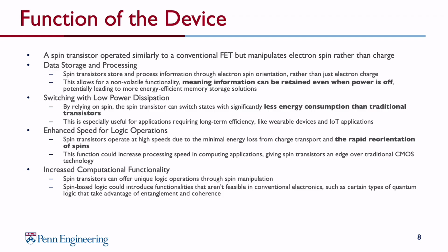A spin transistor operates similarly to a conventional FET, but manipulates electron spins rather than charge. Regarding data storage and processing, this allows for a non-volatile functionality, meaning information can be retained even when power is off, potentially leading to more energy-efficient memory storage solutions. Also, spin transistors can switch states with significantly less energy consumption than traditional transistors.